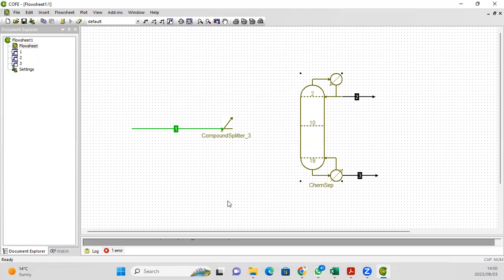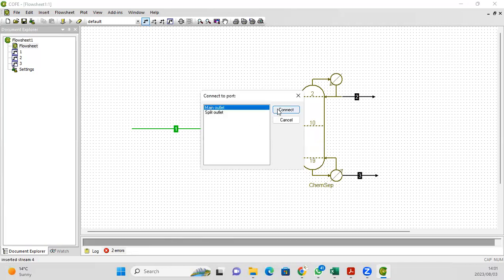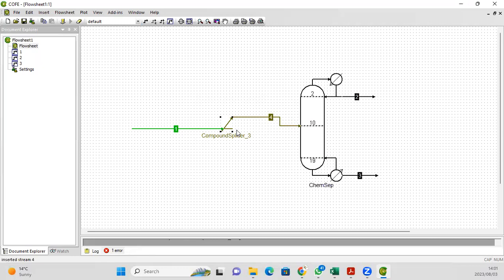It would need a residence time that allows your gases to bubble out of the liquid and appear in the vapor, leaving your liquid being mainly water and acrylic acid. But the point is, I want a stream that only has water and acrylic acid, and another stream that has the permanent gases. So let's just have that going there. Okay, outlet, and then you have your split outlet.